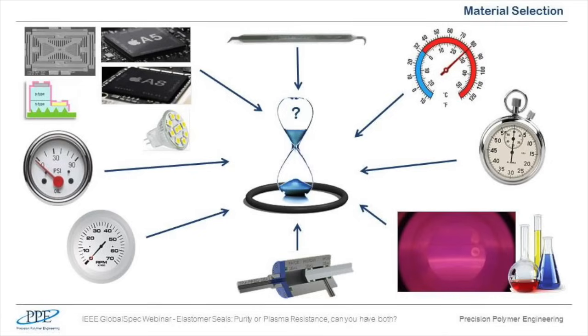But more important than this, it is very good for us to know what kind of end product will be made using this tool. It makes a great difference in the performance and the price of a material. For example, if a MEMS device will be produced in the tool, fully organic, extremely pure, and therefore very expensive material does not need to be used. Traditional filled low-end semiconductor material will do the job. On the other hand, if a 7 nanometer FinFET device, for example, is to be made, just the opposite: to avoid contamination and particulation, the purest possible material needs to be used for that location.